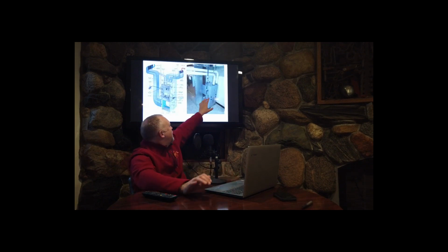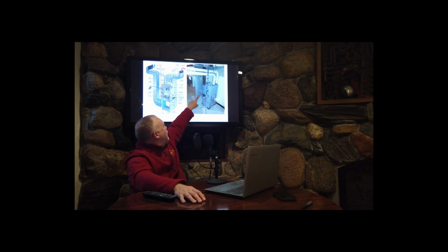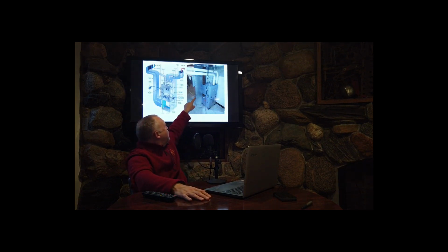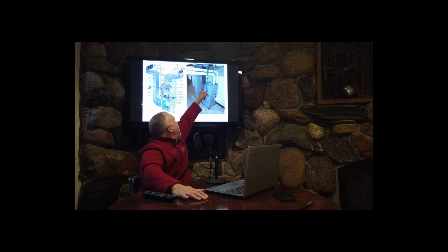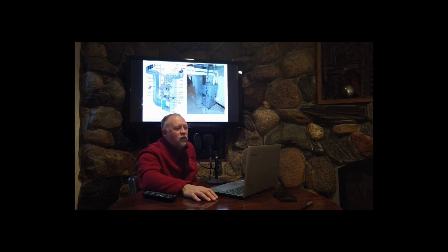Let's take a look, this is a picture of a real one. Here's the return air coming in the bottom. This is just a big metal cabinet so that you can't see all the internal parts. The return air comes in here, goes through a filter, we put it through the heat exchanger, and then the silver ductwork on top goes back to the room.